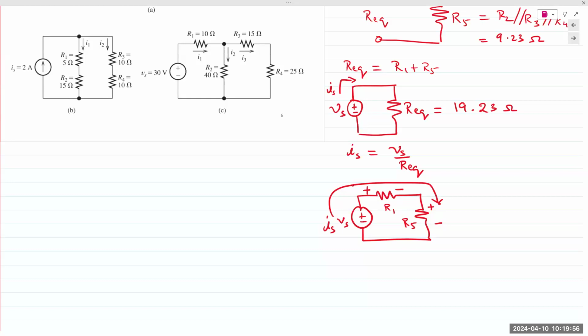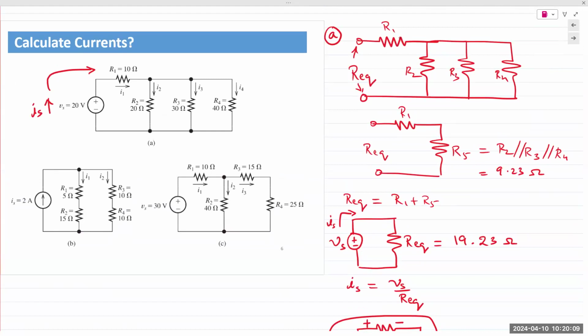Anyway, coming back to our circuit, voltage drop across R5 has a plus up top, minus at the bottom. We call that V5 or VR5, doesn't really matter. And that voltage is across R2, it's across R3, and it's across R4. R5 is a combination of R2, R3, and R4. Voltage across parallel combination is a result of all of those resistors working together. So if it's a combined effort, same voltage, right? So V5 appears across R2, appears across R3, appears across R4.